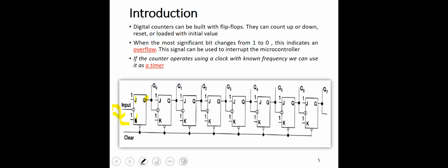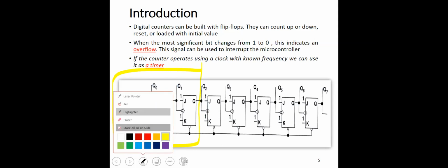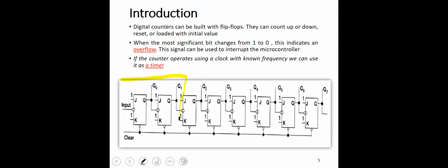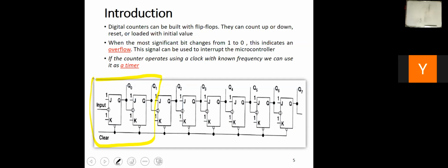Okay, so this flip-flop, the first one, the most left flip-flop, basically changes the stored value on every falling edge. So let me just show the timing diagram for the first two flip-flops, which is basically a 2-bit asynchronous counter. So let me share the video.